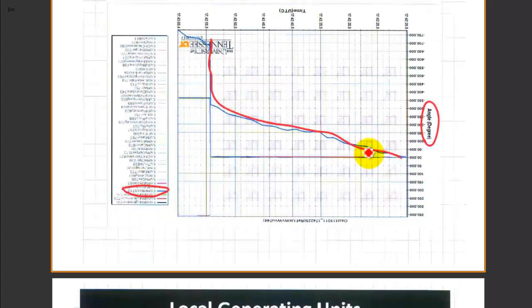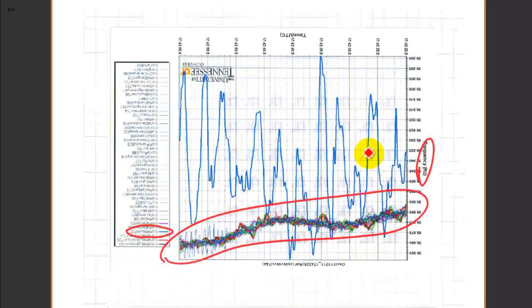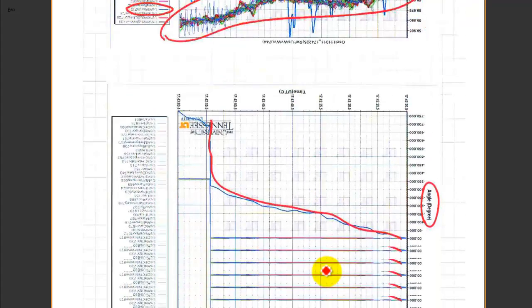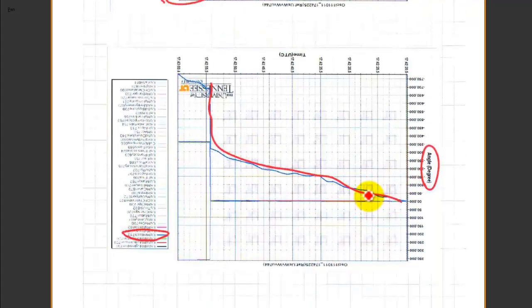So this is the picture I'm showing here. I think this is in the reverse order, but that's fine. We can rotate that later on. The one thing is the frequency information. As you can see, this is all the FDR devices from the rest of the country, the Eastern, to be precise, the Eastern interconnection. And then the blue part is actually showing very, very different from the rest of this. This is what we call not coherent, which means that something could happen, like an islanding. And this is the data, but we get the same thing for the angle information. It's sort of deviating from the rest of the system.